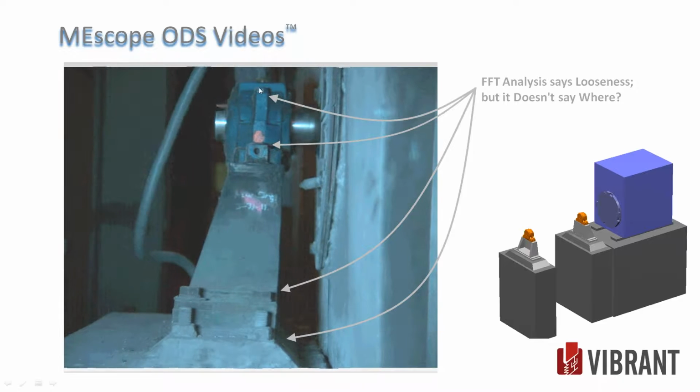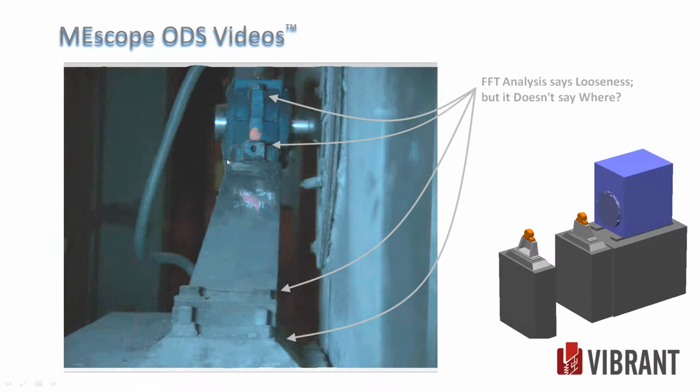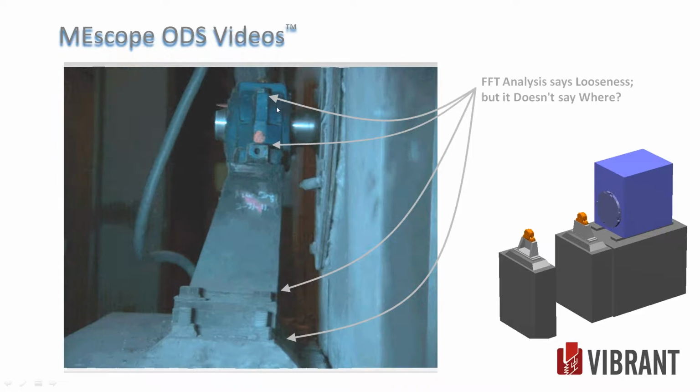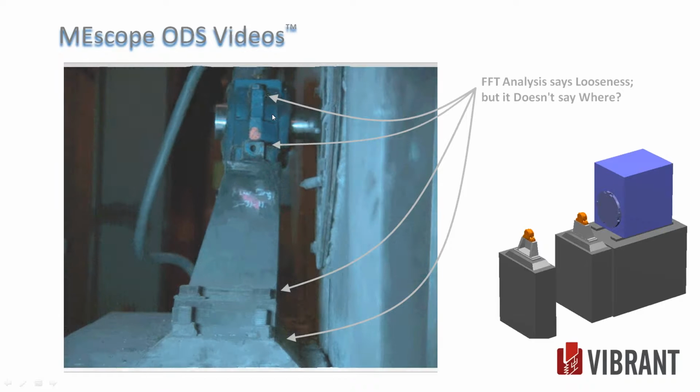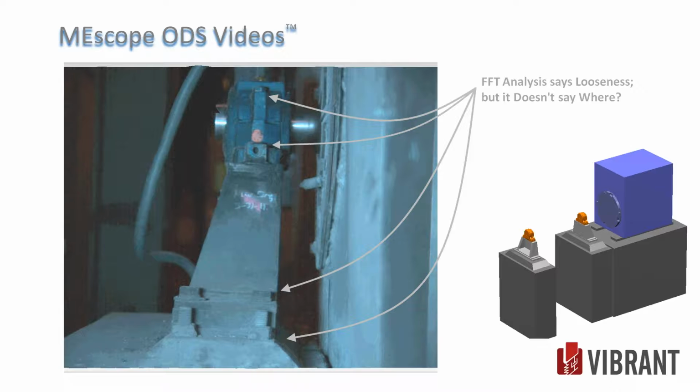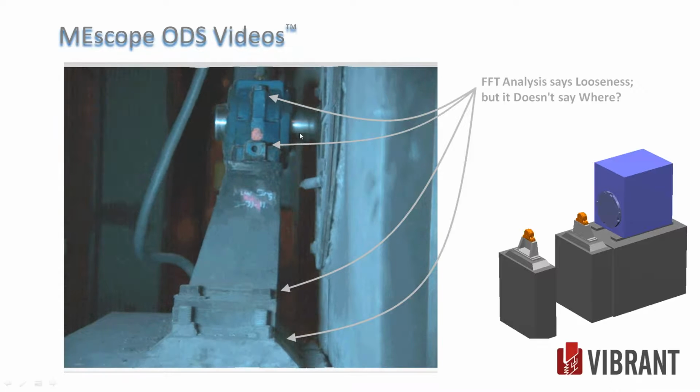It would either come loose on this bolt, this interface. They really didn't check too much down here. They just made sure everything was tight, but they'd over tighten and they'd lose the bearing. They'd under tighten, it'd be too loose, they'd lose the bearing. And they couldn't get the combination exactly right where the bearing would run very long, but they were changing these out every outage. What's interesting here, you can see in the image, the rotation of the shaft and the thrusting of the bearing.